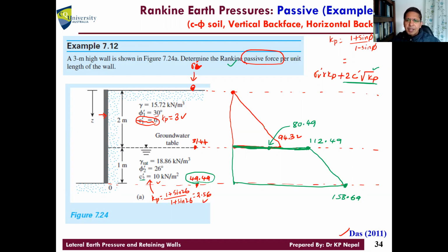All right. So now, can I calculate the area of this now? What will be the area of this triangle first? It's just the total force, so it should be all good. Easy. Oh, there is a water also. You guys didn't tell me. I need to put the water pressure also, another separate one. This would be 0 at the top. At the bottom would be what? 1 times 9.81. So there will be 3 parts: 1, 2, and 3. I need to sum them together.